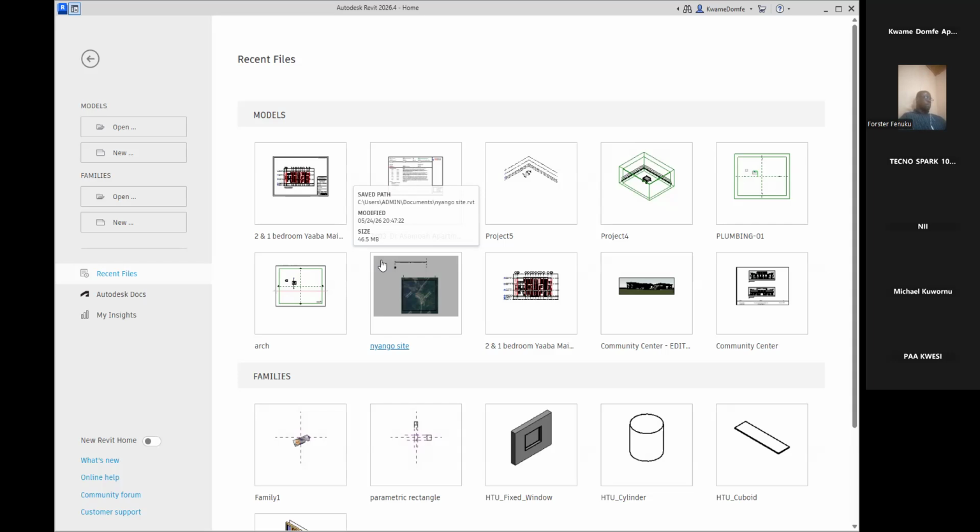But most people did not understand the layout system. So within the same model, they would create all the sheets that they need. Later on, I'll show you samples at the right time. Sheet 1, sheet 2, sheet 3, sheet 4, normally arranged in a nice grid. And when they are ready to print, they draw a window over each sheet and print it out.